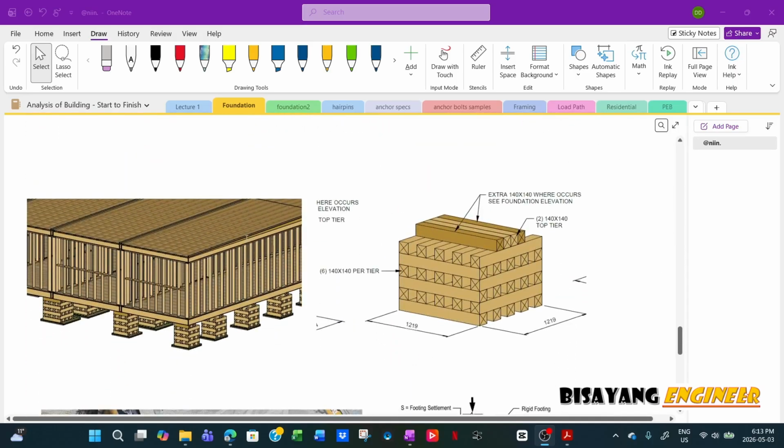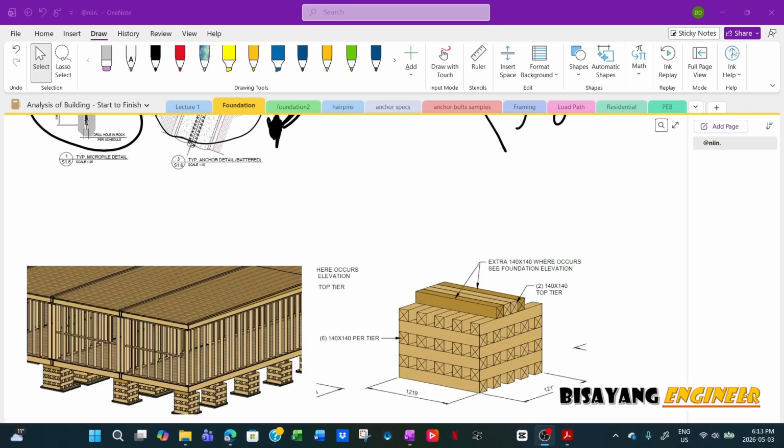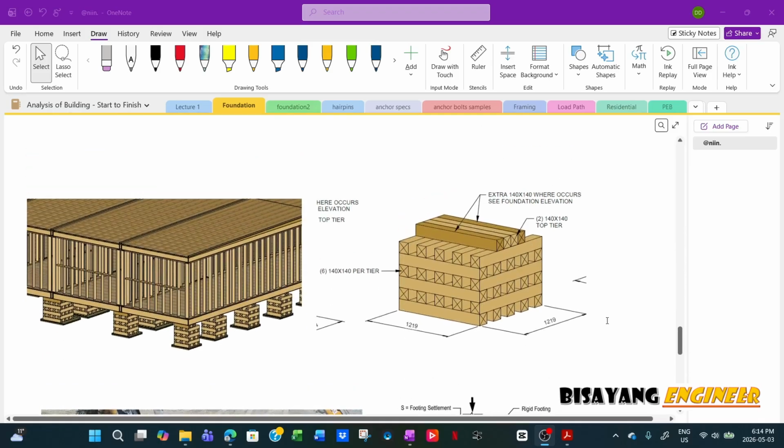And then this is common for pumps in oil and gas. I've designed also a foundation like this one for a residential building. So the critical on this one really is, well, the same. You design the... now there is a, this is the cribbing, and then there's a timber mat. This one has three layers of pressure treated timber mats that serve as a footing. And then this one, the critical check is overturning